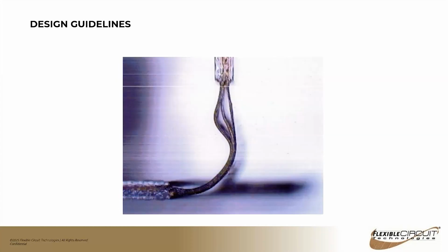One thing you can do is selectively bond the circuits just at the ends that need to be laminated, drilled, and plated together, and leave the rest of the flex straps unbonded. A design like this, which would basically be an unbonded design, can provide significantly more flexibility because the materials are not laminated together.